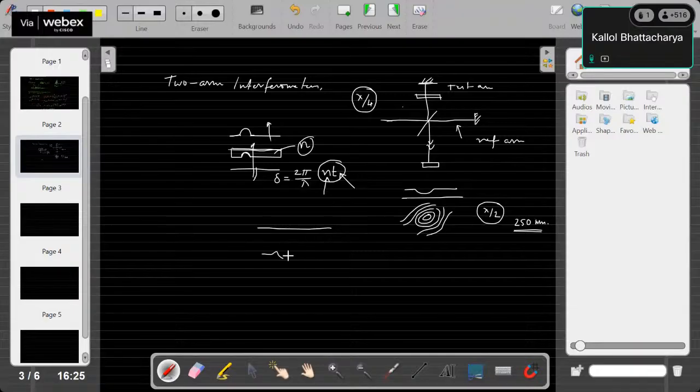It is something like this. If you look under a microscope, or do an AFM of a flat surface, it actually has these variations from flatness. It has certain roughness values. So if the peak to valley deviation is greater than lambda by 4, then it is not suitable for an interferometer, and therefore interferometer optics is so costly.